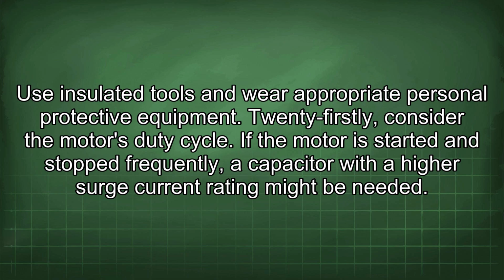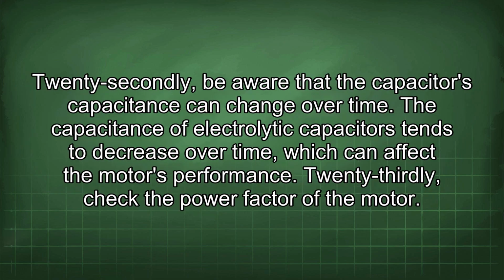21st, consider the motor's duty cycle. If the motor is started and stopped frequently, a capacitor with a higher surge current rating might be needed. 22nd, be aware that the capacitor's capacitance can change over time. The capacitance of electrolytic capacitors tends to decrease over time, which can affect the motor's performance.